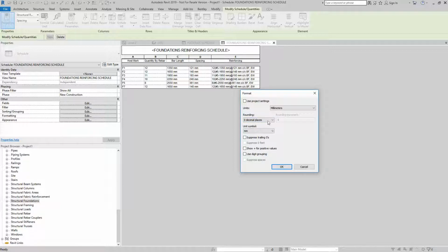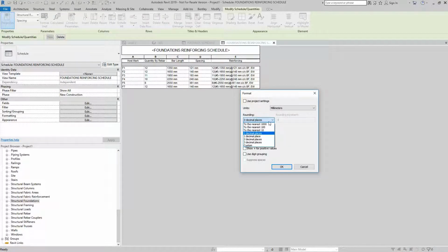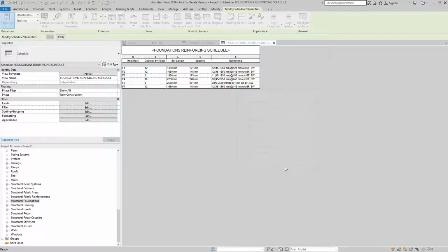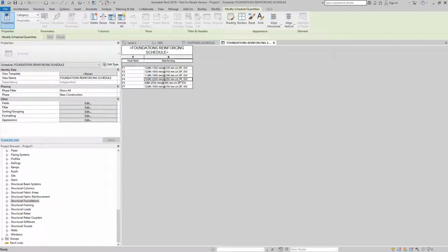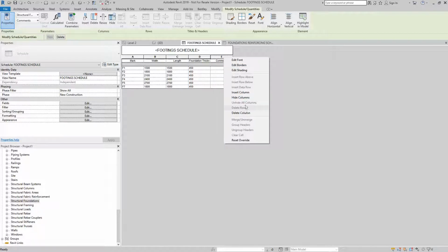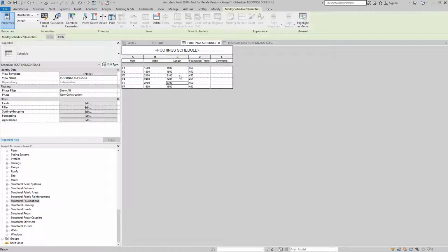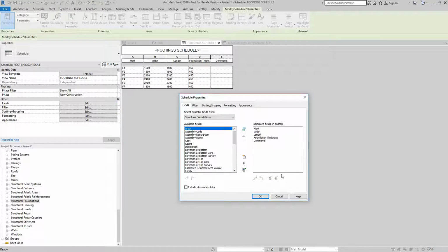So here let's round to the nearest 10 millimeters. For the default, we see it is rounded to the nearest 0. Now we can hide these fields. Now our string reads properly. Nicely rounded numbers. Okay, so we want to, in a way, merge, either present this as two separate tables in our sheet or have that information merged. And we'll see that in the next little bit.